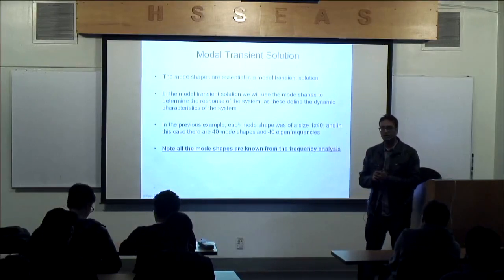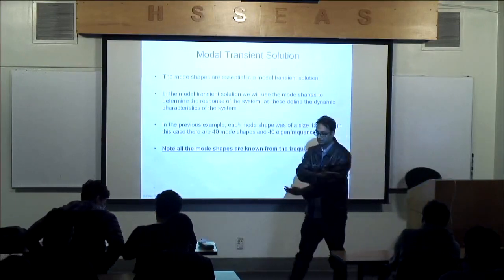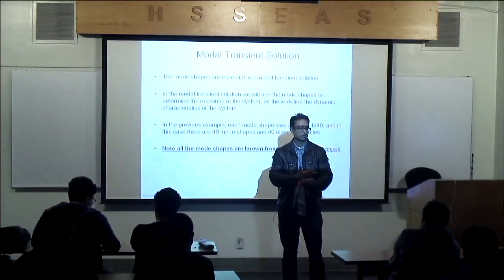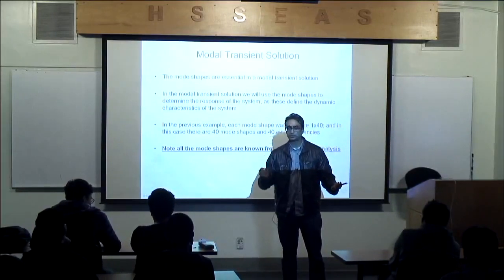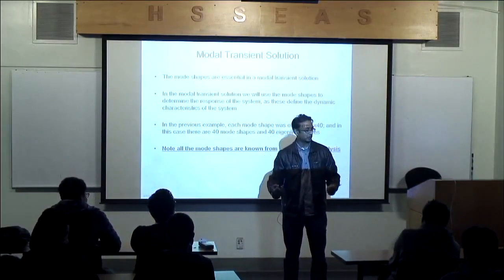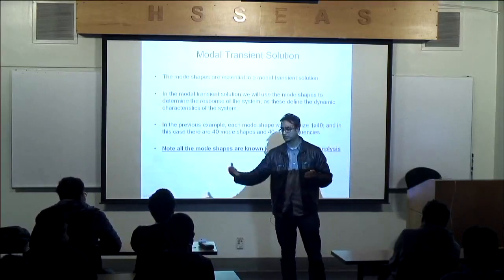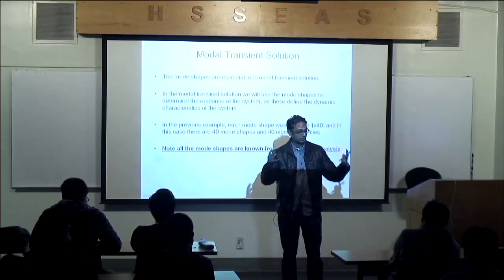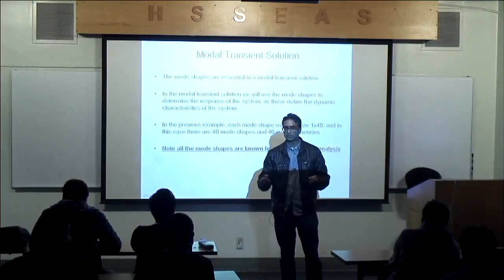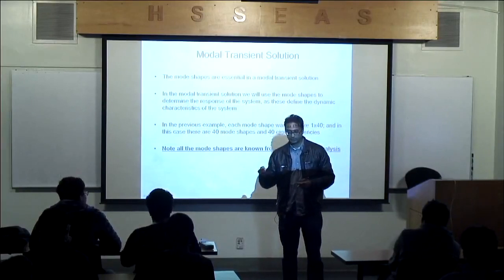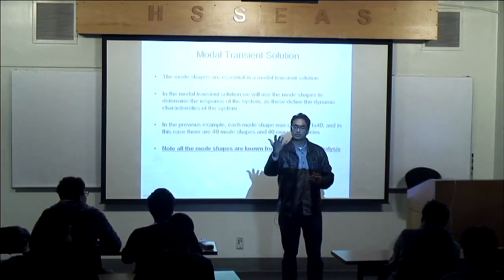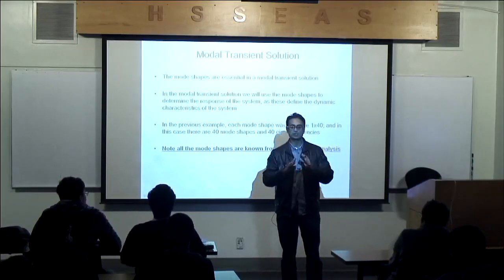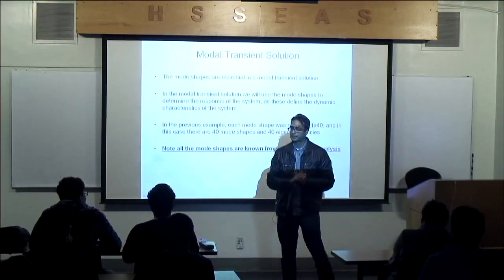I'm going to go to that database of mode shapes and amplitudes. Sorry, I don't have amplitudes, but I have the mode shapes. I know how the shapes should look. I'm going to pull from them and say, maybe my structure behaves like this mode shape and maybe like this mode shape. Well, I can't really do that for a very general problem; that was very hard to do. If I put the mode shapes into finite elements, I'd rather just have the finite elements tell me which mode shapes participate, which ones don't. I'd rather just leave it to finite elements to do it for me.